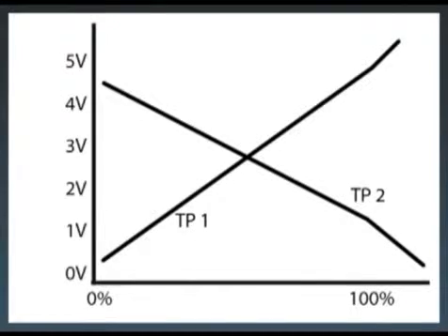The throttle position sensor works differently than on a mechanically controlled throttle. The TP sensor is two individual sensors within the throttle body assembly. Two separate signal, low reference, and 5-volt reference circuits are used to connect the TP sensor and the PCM. On the earlier systems, TP sensor 2 signal voltage increases as the throttle opens. TP sensor 1 signal voltage decreases as the throttle opens.